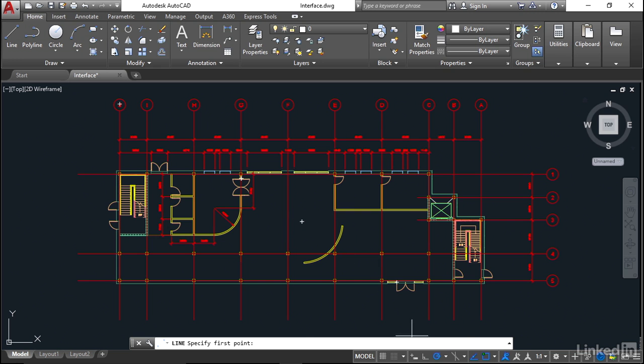And I can go into the middle of a command and switch it on. And as you can see, the prompt is back on the crosshairs again. That's the whole idea of the status bar, is you can go in and out of it at any time when you're working in a command in an AutoCAD drawing. So I'll just hit escape there to cancel the line command.